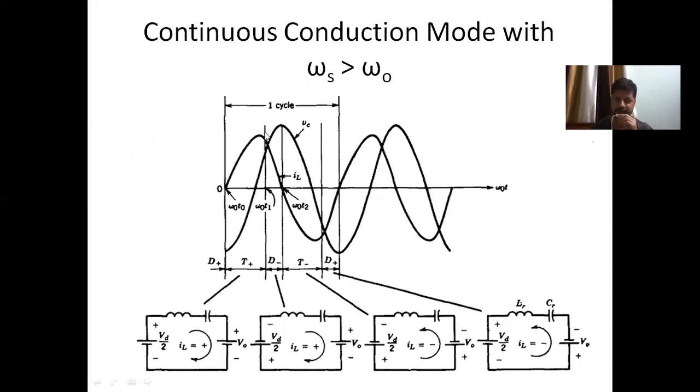As you can see, if this had followed, it would have reduced to zero after some time, but because of the large negative voltage applied across the LC tank, and D minus is conducting, the current will be close to zero earlier.